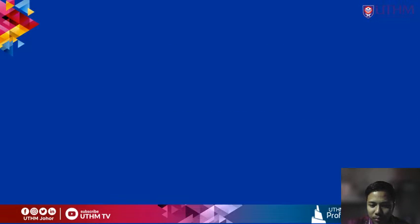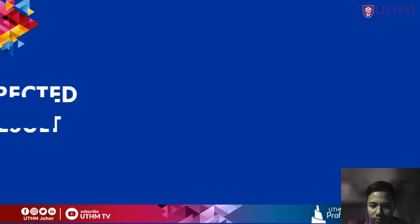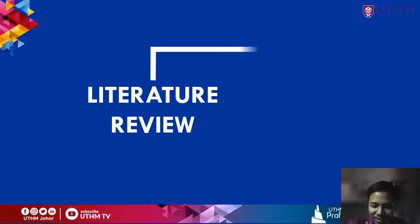My project scope is a container built with a NodeMCU ESP32, soil moisture sensor, light sensor, and temperature and humidity sensor. This project will be equipped with a cooling and heating system, artificial light system and moisture system. The sensors will be read by the user through an Android application, Blynk, via Wi-Fi module. For a start, the project will apply to a smaller scope first, using a chili plant. Skip the expected result.